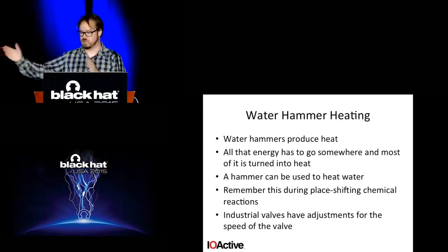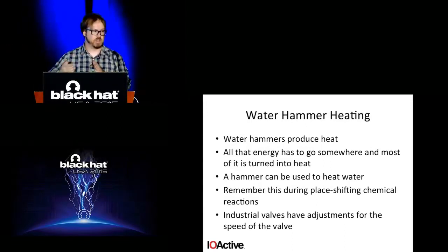And if you open it and close it again and it slams to a halt again, you get heat again. So by cycling the valve, you can actually heat the chemicals, which is very useful in shifting the chemical reactions from someplace to someplace else. You can actually use the water hammer effect to heat the liquid.